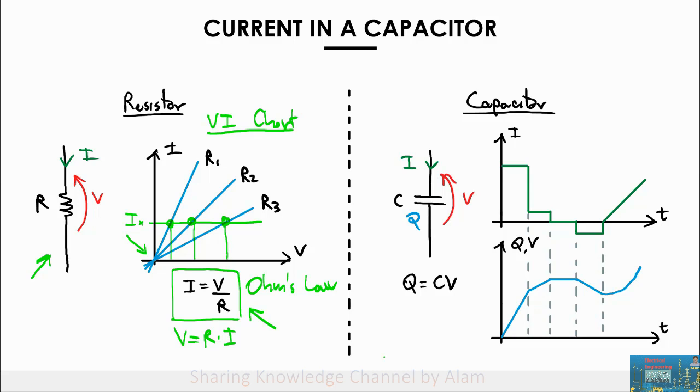For the most mathematical view, you can also note that there is a relationship between the slope of the curve and the equation, because Ohm's law is just a linear equation. So the V in this case is the independent variable, which is the horizontal axis. The current is the output of the equation in this case. And you can see that usually a straight line is represented with an equation that is mx plus q, where m is the slope and q is like a fixed constant. So in our case, the q is 0 because the current is going to be 0 when the voltage is 0. But our m in this case, which is a representation of the slope, is 1 over R.